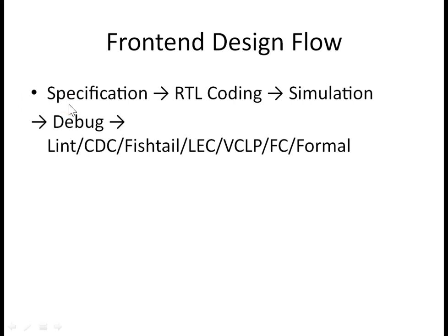Okay, so the next flow is CDC. CDC is clock domain crossing, where we make sure that when data is traveling across asynchronous clock domains, it is transferred correctly and data should not be lost. In an SOC there are multiple blocks in the design with different intentions, and their clocks are different, because there are gaming blocks, calling blocks, or music blocks. There are different blocks in the SOC.